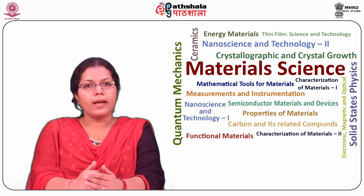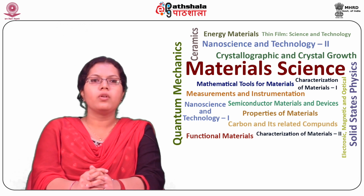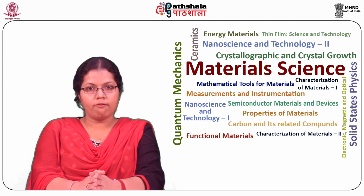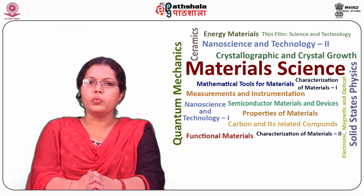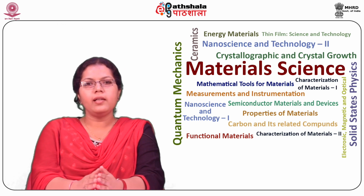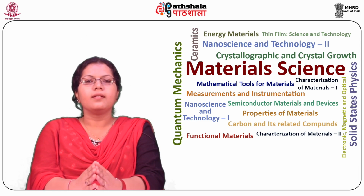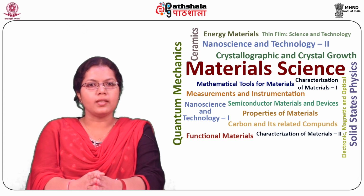We saw that three types of constructions have been used for primary standards of capacitors. First, two concentric spheres. Second, two concentric cylinders. Third, two parallel plates with guard rings. Out of these, parallel plate construction is normally not used, and the concentric cylinder construction has been discussed in the module.